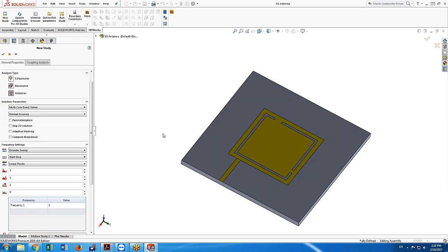We think about structural breakdown, but there is also electrical breakdown when the dielectric cannot support that electric field, and then you're going to start having corona and sparking. And mind you, it's rare in the antenna application, but it's there for you.